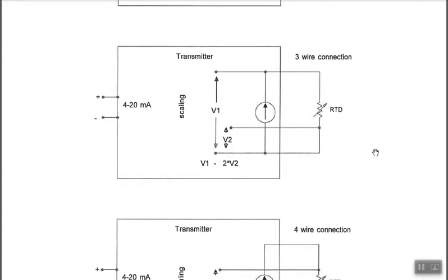So that's the 3-wire connection. And again, if you have a 4-wire RTD, no need to panic, right? You're just going to need 3 of those 4 wires. The extra wire here, cut it off, tape it up, whatever. You don't need it.